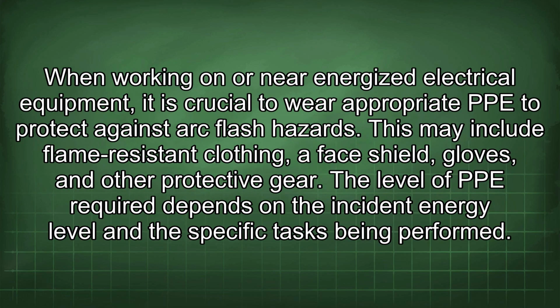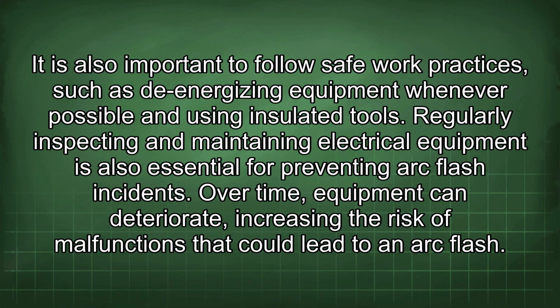When working on or near energized electrical equipment, it is crucial to wear appropriate PPE to protect against arc flash hazards. This may include flame-resistant clothing, a face shield, gloves, and other protective gear. The level of PPE required depends on the incident energy level and the specific tasks being performed. It is also important to follow safe work practices, such as de-energizing equipment whenever possible and using insulated tools.